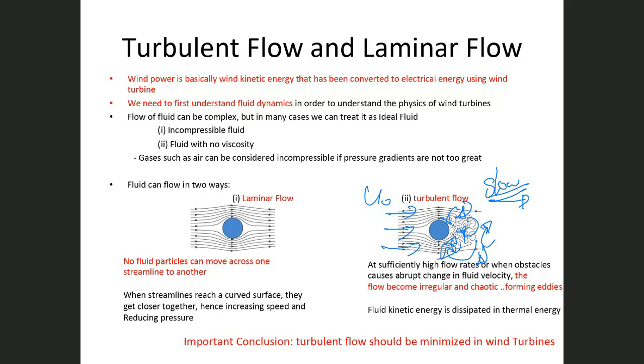This is what we call thermal energy of the fluid elements inside. So the important thing is that kinetic energy is lost as thermal energy in turbulent flow, and this is very important when we're looking at wind turbines. You always want to minimize turbulence as much as you can. Turbulence in wind turbines is an enemy. It should be avoided or minimized.